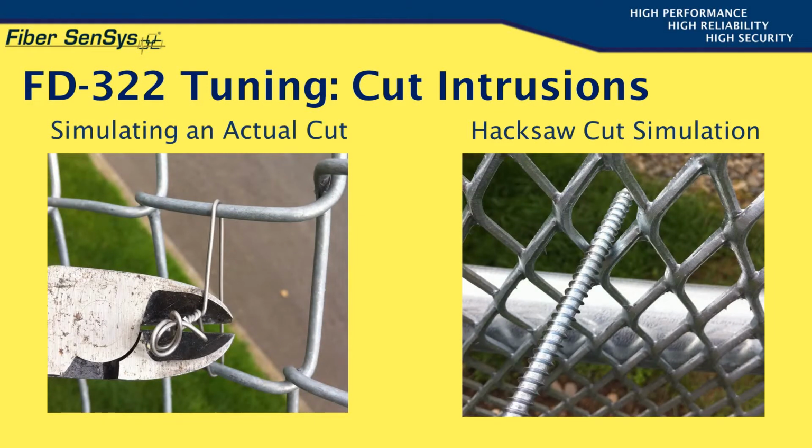Finally, there are several other ways to simulate cut intrusions that may be appropriate for your site. Customers will generally frown upon your cutting their fence when tuning for intrusions. However, a good way to simulate an actual cut is to first tightly attach a stainless steel wire tie around one of the fence diamonds and then cut the tie with a good pair of wire cutters. This is more time-consuming than tapping with a screwdriver, but more accurately simulates a cut. And if you're worried about someone cutting the fence with a hacksaw, you can use a long, threaded screw or bolt that's dragged back and forth through the fence to simulate such an intrusion. This concludes our discussion of FD322 calibration and tuning.